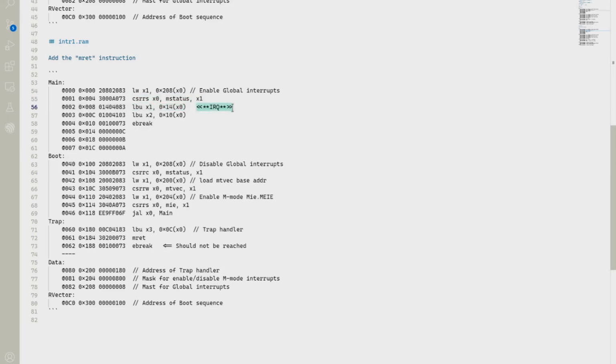This is, again, the one we put in our C++ test bench. As soon as it gets there, it will hit the trap routine down here. The prefetch will detect the interrupt and set up and call the trap vector. And now remember, we loaded the mtvec with 180, so when that interrupt occurs and it calls the trap vector, it knows where to go.